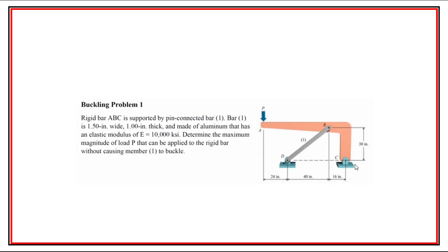because it makes the exams too long. There's also buckling. So here's a buckling problem. I think I have asked a buckling problem before, so I think reviewing it is worthwhile. For a buckling problem, what I would be looking for was that you at least checked to see if it was slender or not, considered Johnson or Euler, and then used the correct one for them.